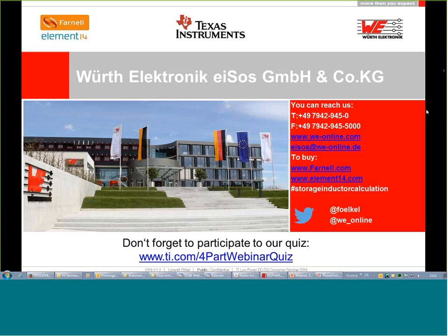It depends on the application, honestly. I did also use a DC-DC converter when I made my own mixer at home. I had no problem because I knew what I was doing with my DC-DC converter. And of course, I put in some more effort, not just a simple LC filter, but with a simple PT decade, you can always filter the residual ripple until you have less than 5 millivolts ripple. And if 5 millivolts is fine, I don't know if I would choose an LDO just for 40% or less efficiency.